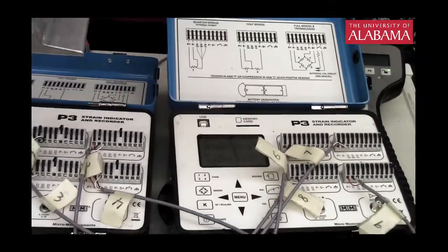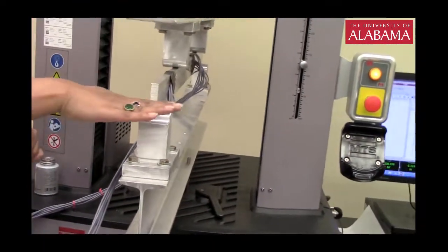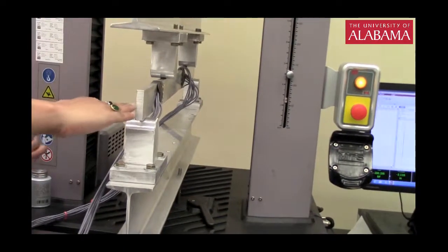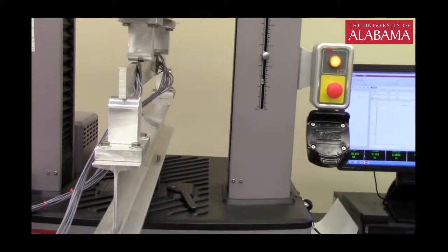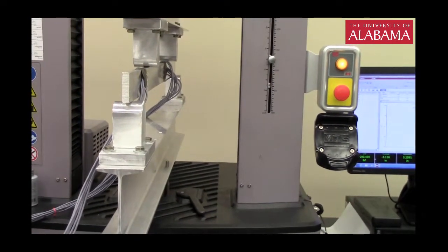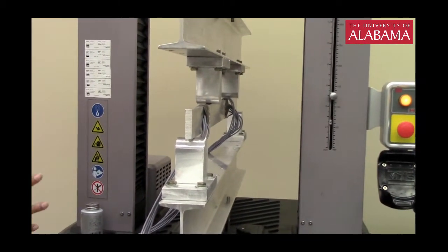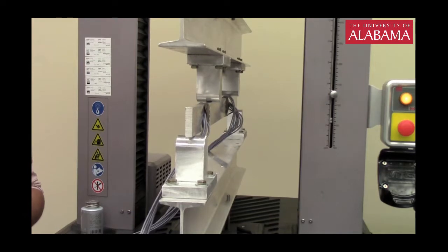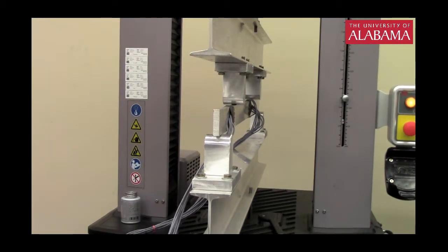Now why is it so? If you imagine, when I am putting a point load on the beam, it is bending like this. The region over here is the neutral axis. Anything above the neutral axis will have compression, that means it will have negative strain. So the first four gauges are in the compression zone, so the gauges read negative. The other gauges, the 6th through the 9th gauge, are in the expansion zone, that is beyond the neutral axis, towards the bottom. So it is stretched out, so it has a positive strain.